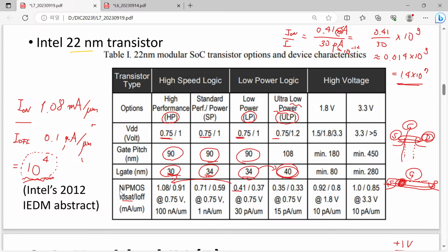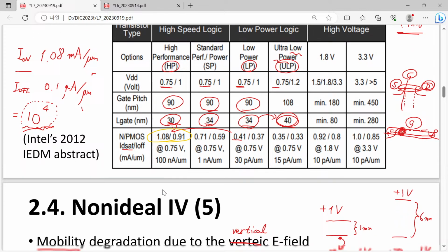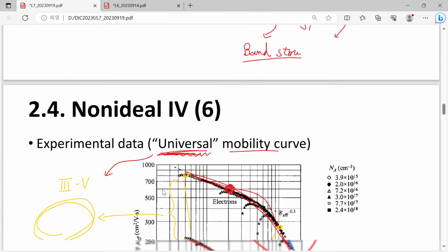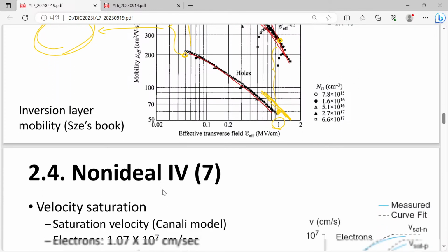We must always care about PMOSFET because it has lower performance, so in order to boost it, we must widen it. However, as technology evolves, the gap between NMOSFET and PMOSFET is not as severe as in the textbook example. Okay, that is one thing.